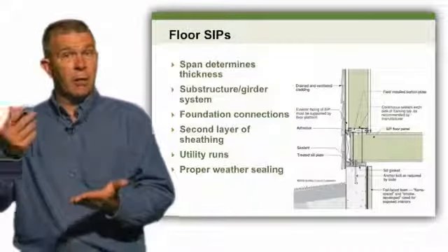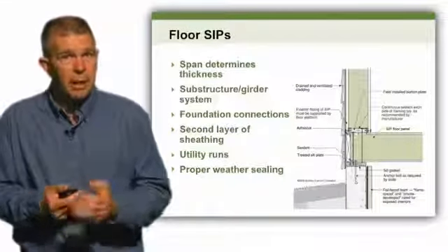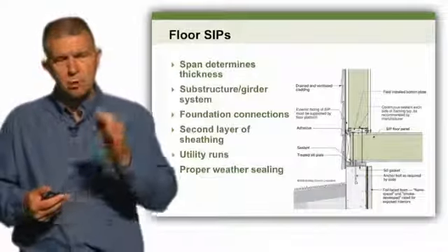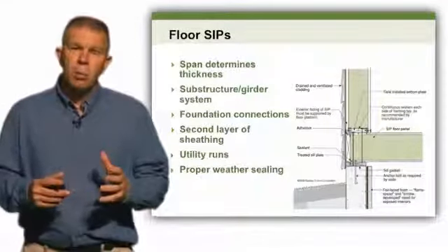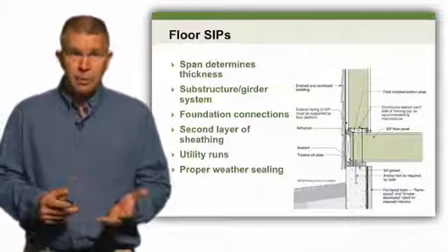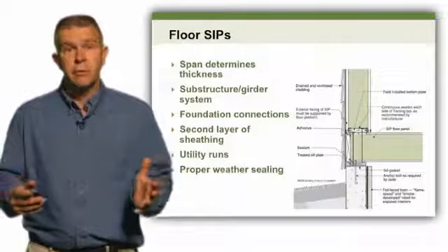And then if we put another layer of sheathing on top of that panel, we're now talking about trapping moisture. So it's really important before you consider using these floor SIPs. So the designer, when working with floor SIPs, needs to determine all of those various things.